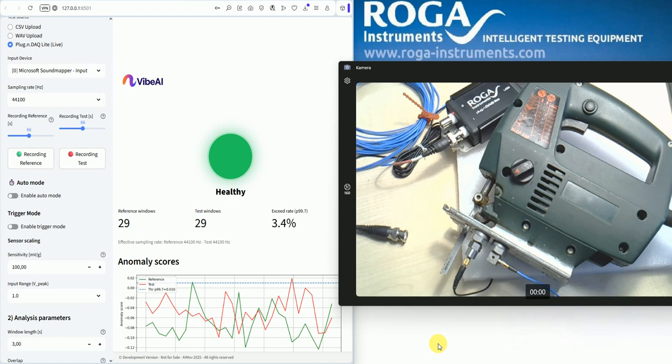For example, if we have a very small accelerometer, then it has relatively high inherent noise. An accelerometer with 1 or 2 grams weight has inherent noise of about 3000 micro G. This kind of accelerometer has 100 millivolt per G sensitivity. It's uniaxial. The better ones are in the area of 300 to 400 micro G.